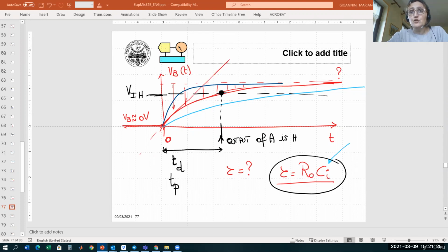Then there's a question from Giacomo Zanella: but doesn't this mean we are inputting forbidden voltage levels at the inverter input while the capacitance reaches VDD? Yes, but it doesn't mean that you're inputting forbidden levels. It means that you have a transient, as shown here. So you have this time interval where voltages are neither high nor low.